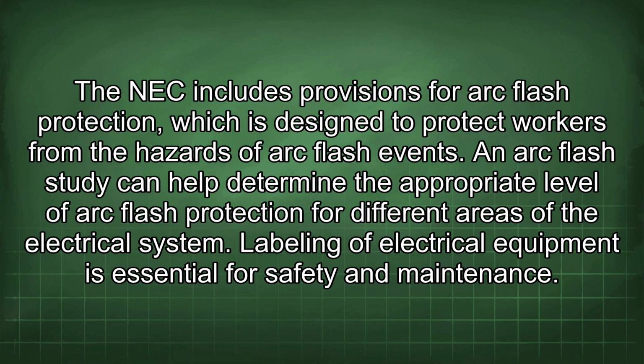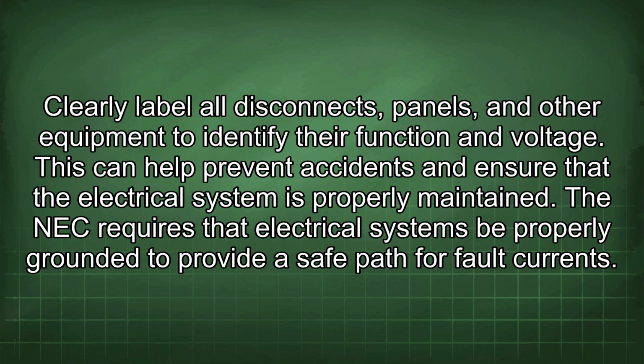Labeling of electrical equipment is essential for safety and maintenance. Clearly label all disconnects, panels, and other equipment to identify their function and voltage. This can help prevent accidents and ensure that the electrical system is properly maintained.